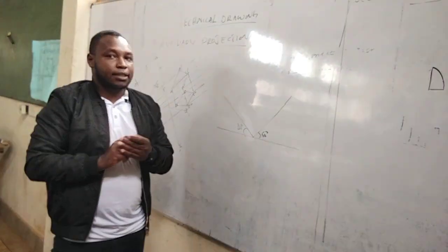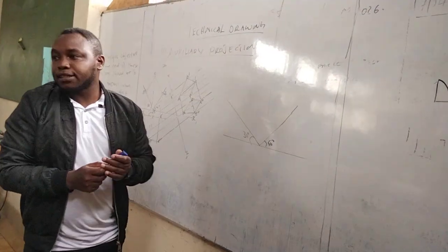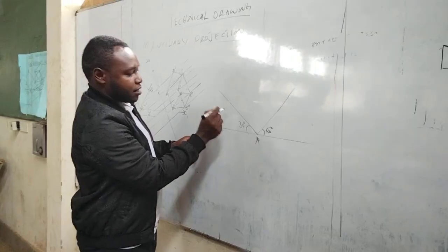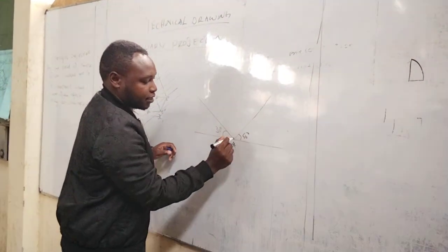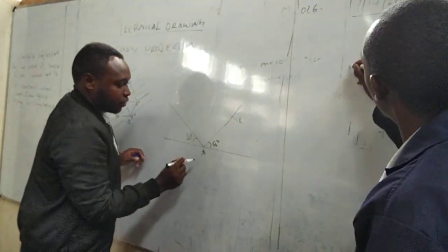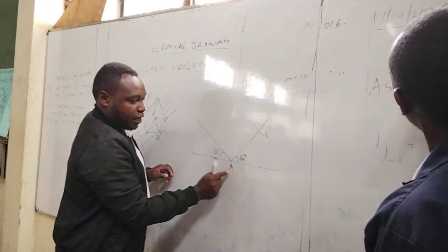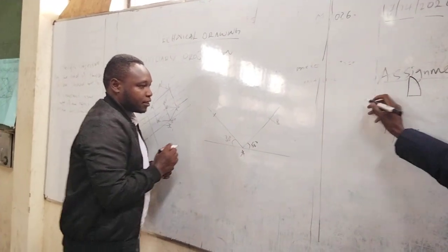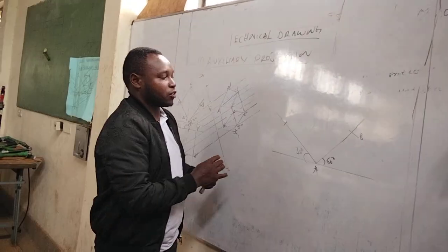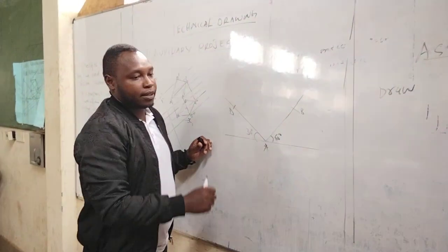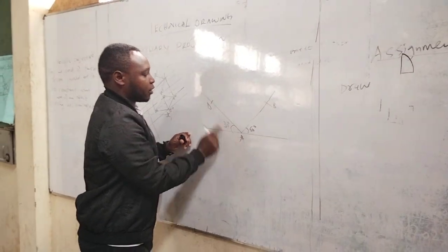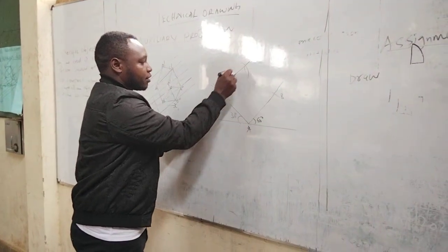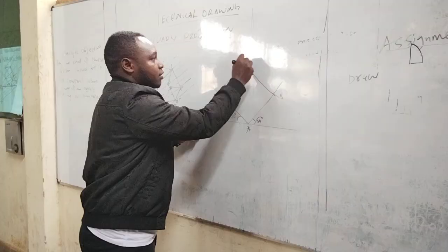Now, you measure the distance from point A to point B on this other side. You mark that point B, and AB should be the distance to AD that way. So using a pair of compasses, you stand at D this way. You mark an arc, that is the distance from A to D. Stand at D, mark an arc, stand at B, mark an arc. Then you join, and we call it C.